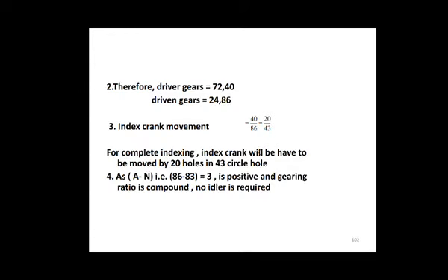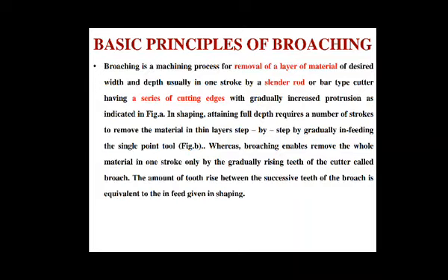So these are the basic principles of broaching. It is a machining process for removal of a layer of material of desired width and depth, usually in one stroke, by a slender rod or bar type cutter having a series of cutting edges with gradually increased protrusion, as you can see in the figure.